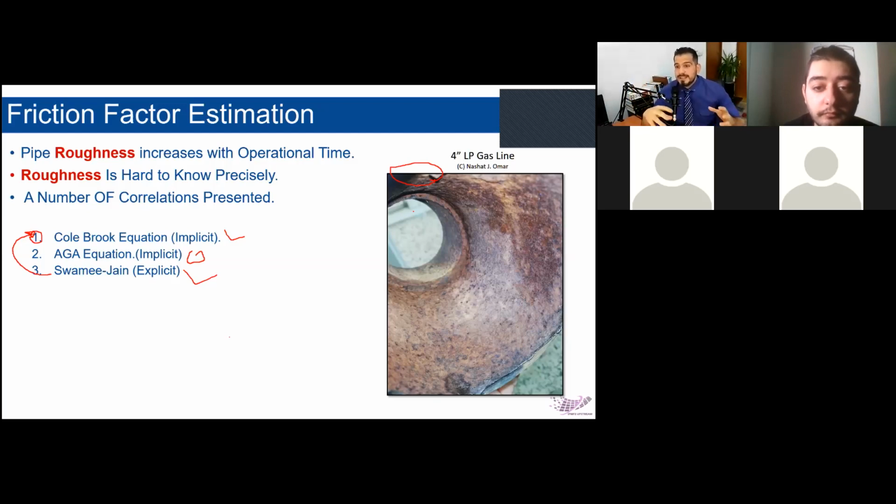The first dynamic model is the radial model. You can have it at any extent you like, maybe 1.5, 2, or 3 kilometers. It's all up to your preferences, and you can distribute the saturation in it as well. You will put the wellbore inside it, and you will optimize your choke sizes based on that. Whenever you have the well choke optimized, you can monitor what's happening near the wellbore. In that area, you will know for sure whether you are having coning or not. So the key answer is yes, you can use OLGA. However, you need to attach a rock model to it.